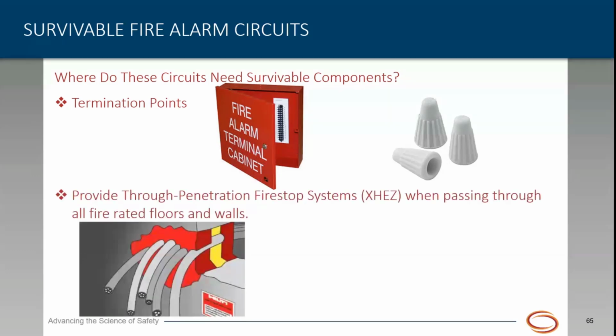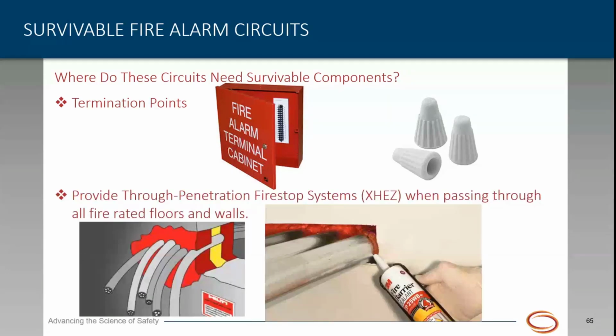And then, of course, you have to remember all your through penetrations have to be fire stopped when passing through fire rated floors and walls. And even though that's not normally your job as a fire alarm installer, you need to be aware of it.